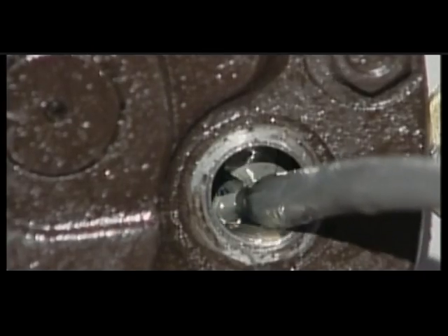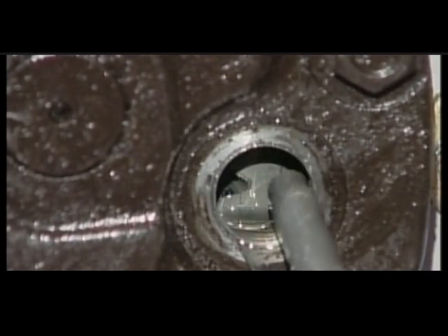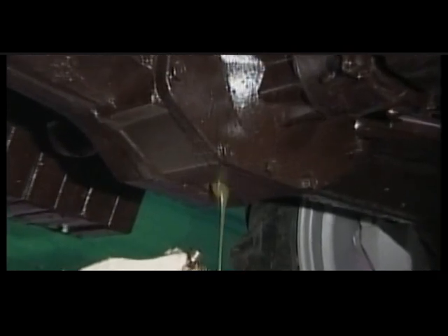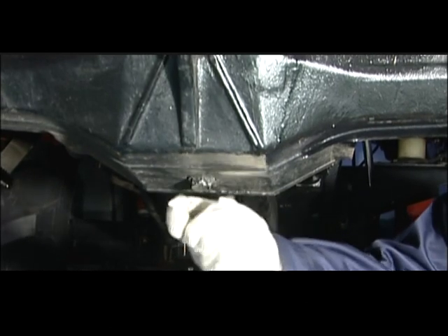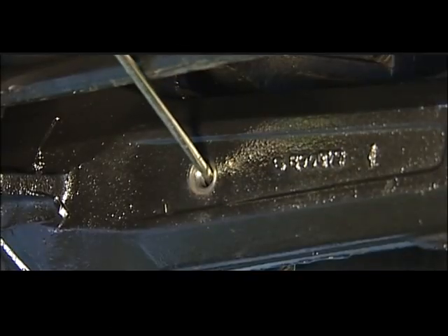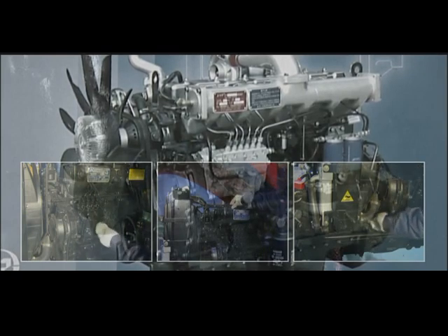Turn the wheel hub again. Keep the plug orifice at a horizontal position. Refill new oil to the plug orifice. When changing the front drive axle housing oil, drain the dirty oil from the drain plug. Retighten the oil drain plug and refill with new oil. Maintain the engine according to the manual.